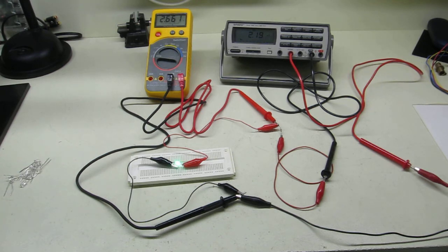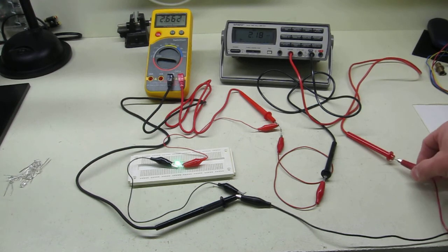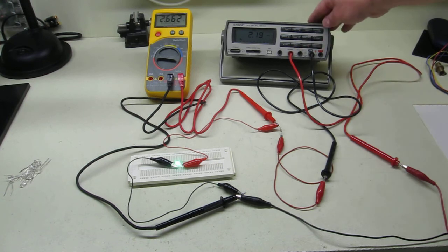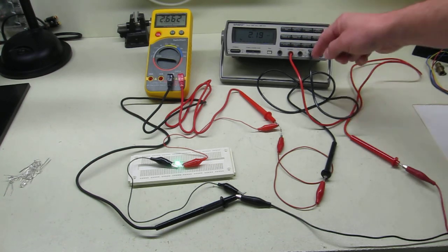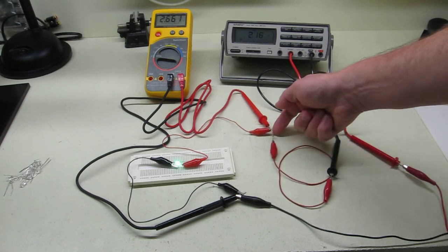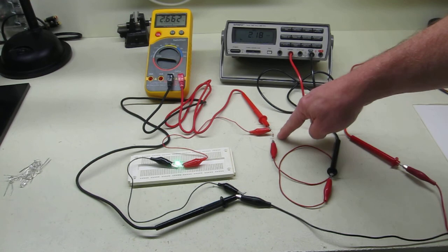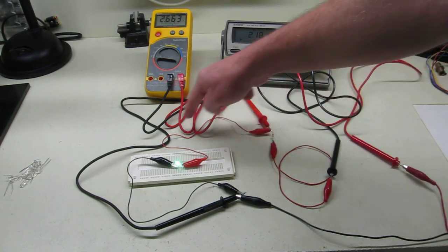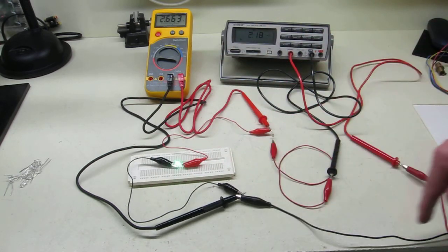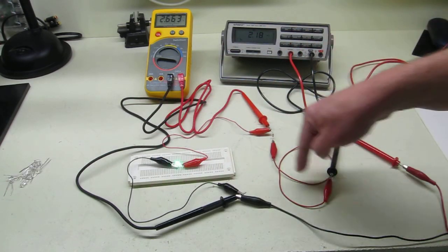The setup, electrically speaking, is fairly simple. I have a power supply just out of the frame here, which produces a variable voltage from 0 to 30 volts. This is the positive lead from the power supply, which goes through an ammeter in series. The output from the ammeter then goes to a resistor, a dropping resistor, about 330 ohms in this case, and then to an LED, and current returns via the black wire. So here is the simple series circuit for the LED.